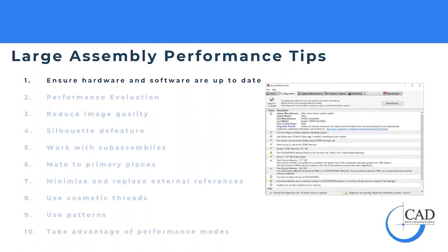all of that is going to load right away, and it's going to tell you if you're using the correct graphics driver. That's a big thing. Using the correct certified graphics driver is one of the biggest things I can recommend. Slowdowns, weird graphics performance, those are all usually the result of using a non-certified graphics driver for SOLIDWORKS, okay? So this is one of the situations where I come in, I check to make sure that the graphics driver is up to date.